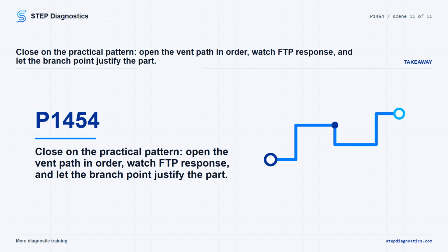Work the checks in order. Use the HDS status to decide whether the failure is active, intermittent, or not finished running, and do not replace parts until the branch points you there.